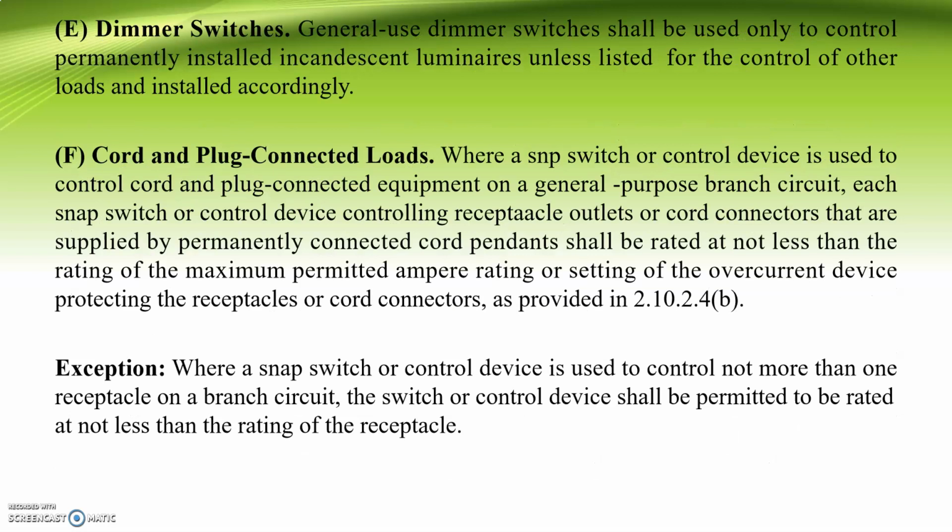E. Dimmer switches. So general use dimmer switches will be used only to control permanently installed incandescent luminaires unless listed for the control of other loads and installed accordingly.